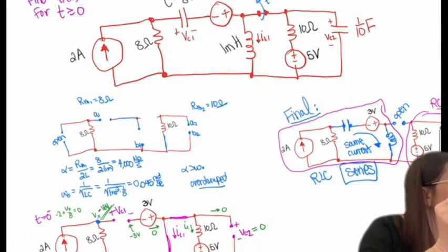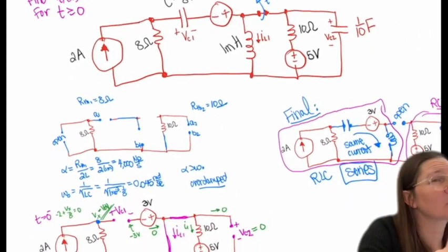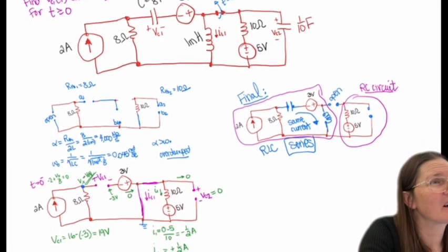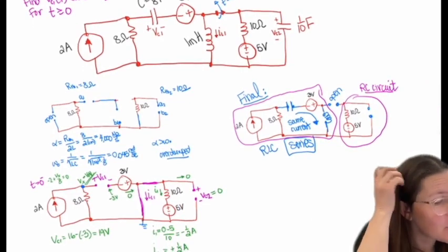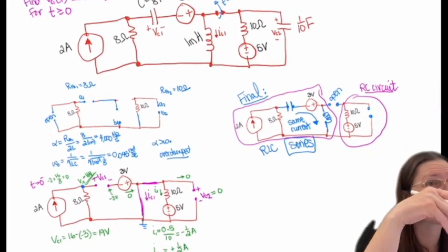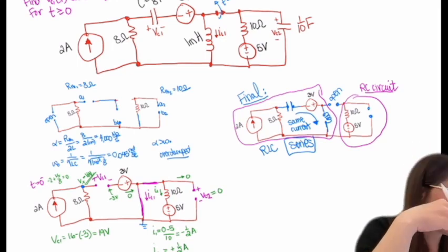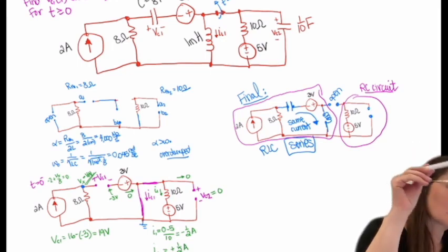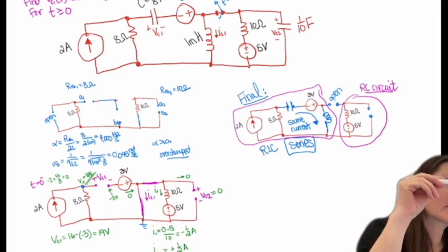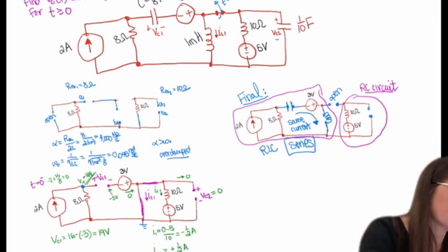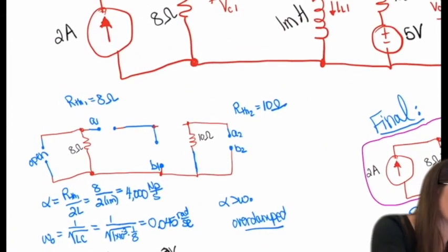All right, so I have two problems, so we're gonna move through this pretty quick. So RC side and then the RLC series side. On the final position will be where you're going to find RTH. So RTH for the RLC series will be 8 ohms. Why am I finding the RTH, by the way?